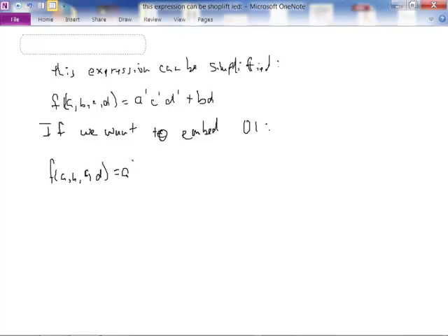So our original terms remain A naught B, C naught D naught, or A naught B, C naught D, or A naught B C D, or A B C naught D, or A B C D. Okay, so now we've included this term A B C D, which is one of the don't care conditions, so that will return a 1, but we didn't include the other don't care condition, A naught B naught C naught D naught, so now we've hidden the information 0, 1.